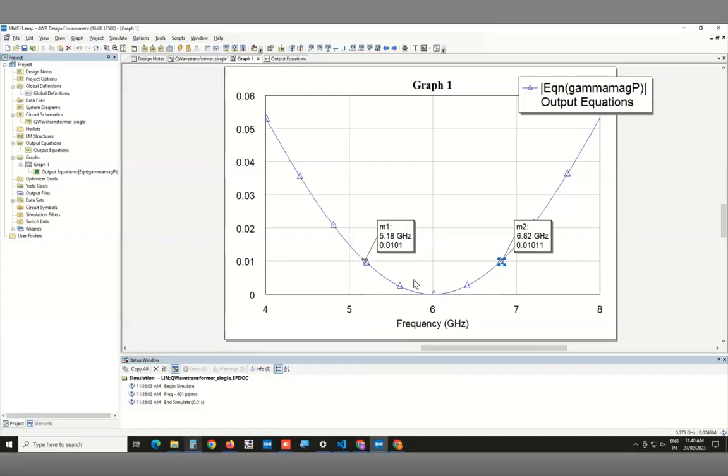So this is again like a standard thing we had discussed, that we usually consider 1% reflected power as sort of considered a small reflection. So anything which is better than that, it's good. And beyond that, it's not so good. So we can say that the impedance transformer works over this particular range.